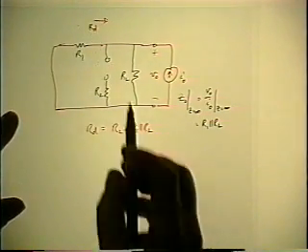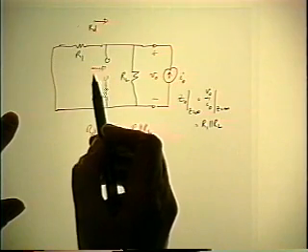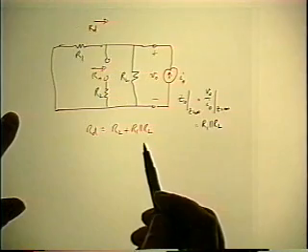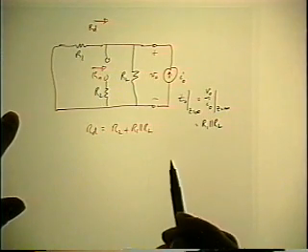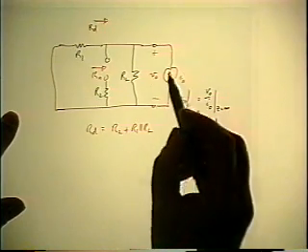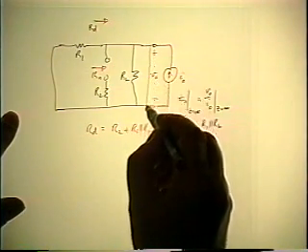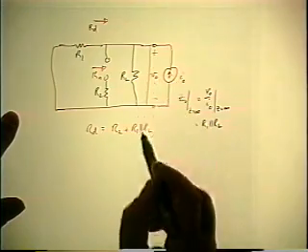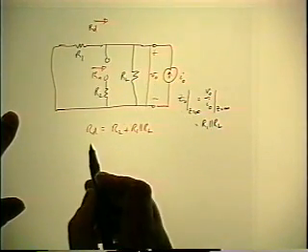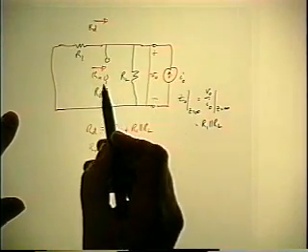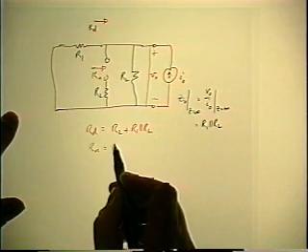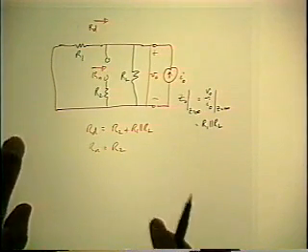Second calculation: apply the independent source and find R_N under conditions that the output is nulled, which is equivalent to shorting the input. The input is the I_O. When you short it, the V_O is 0. So when you look in now for the R_N, you're going to get only R2, because you've got a short across the rest of it now. So that's the result.